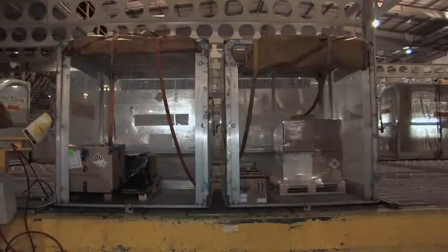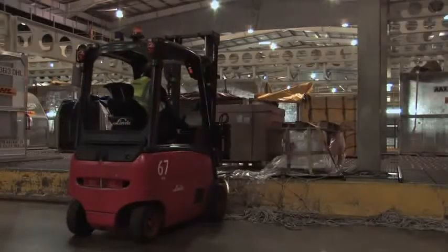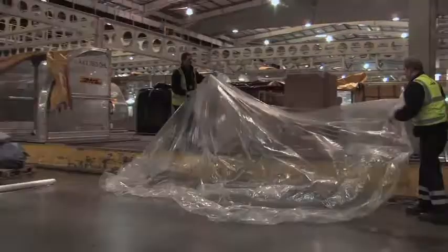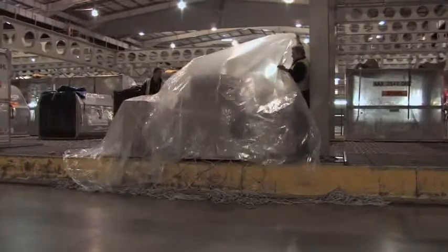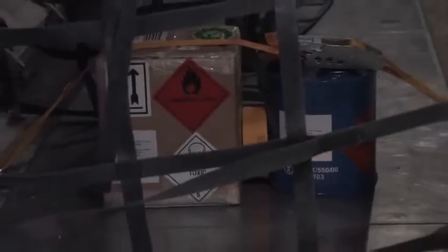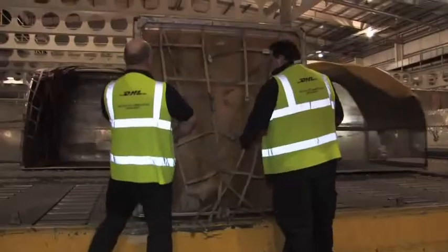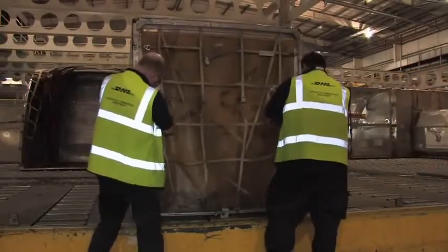Otherwise, they may become a danger to the aircraft and everyone on board. Before loading, always inspect packages for any evidence of leakage or damage. Whether dangerous goods are to be containerized or bulk loaded, they must be secured to prevent any movement and also be protected from being damaged by the movement of other load on board.